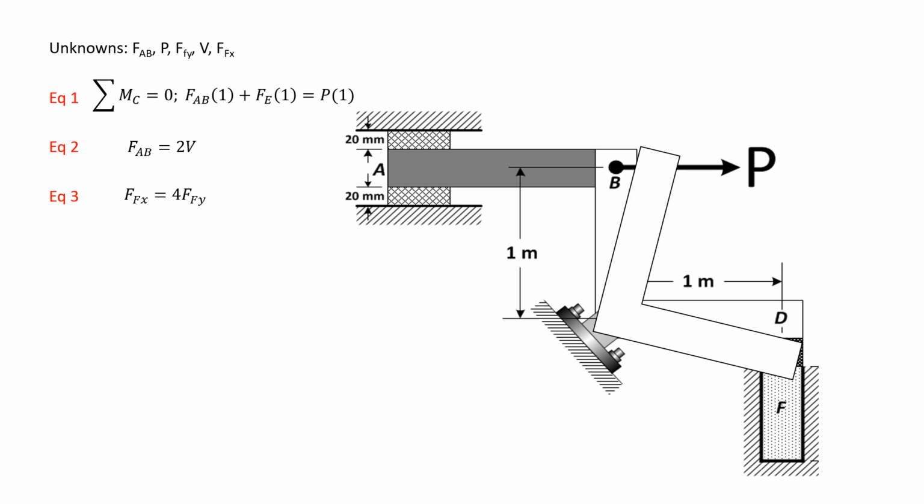Of course, it will not go down. The point C will not go down or move horizontally because of the pin connection. But point B moved horizontally by small angle approximation, of course. And also point D moved vertically downwards. So the movement of point D vertically downwards equates to the deformation of F rather, along the y-axis because E is rigid. So it will not deform. So the downward movement of point D will just equate to the deformation of F along the y-axis.